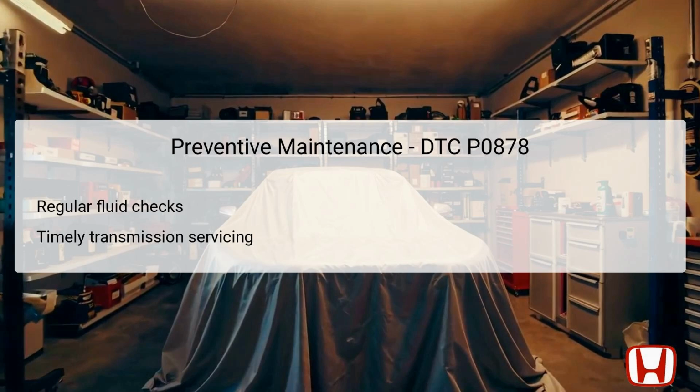In preventive maintenance practices for avoiding issues such as DTC P0878, it's vital to conduct regular checks of the transmission fluid. Ensuring that the transmission fluid levels remain within the recommended range is critical to the operation of the hydraulic systems within the vehicle. Additionally, changing the transmission fluid at the intervals specified in the owner's manual will help maintain suitable hydraulic pressure in the system, preventing excessive wear on components like the fluid pressure switch.